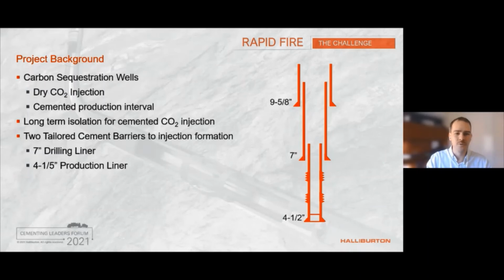The acid is produced from CO2 injection, as CO2 dissolved in water produces carbonic acid, which can chemically attack the cement matrix, producing dissolvable products, which can then be whisked away by water and continuously erode your cement barrier.